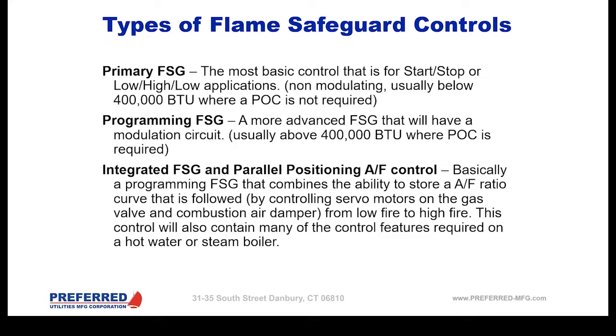And you'll also see, and has become more and more popular these days, the integrated Flame Safeguard and parallel positioning air-fuel ratio control. So it's all integrated into one package. Now, a lot of these packages will have separate microprocessors, one for the Flame Safeguard built into it and the parallel positioning, keeping those two functions separated. Some are not, most are.